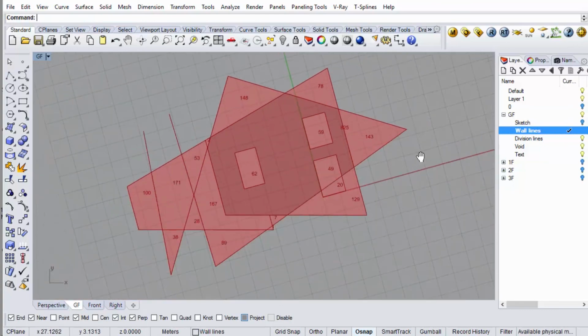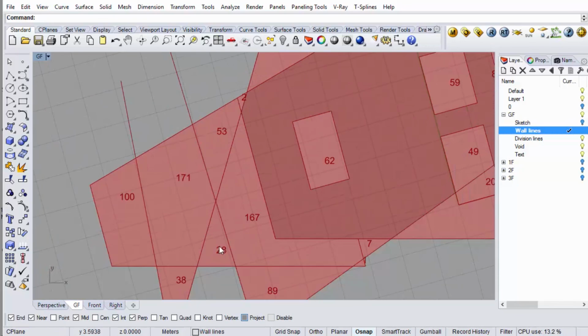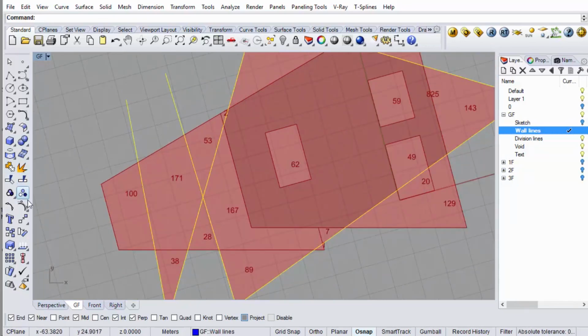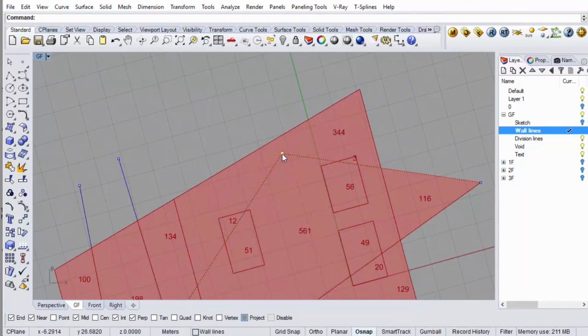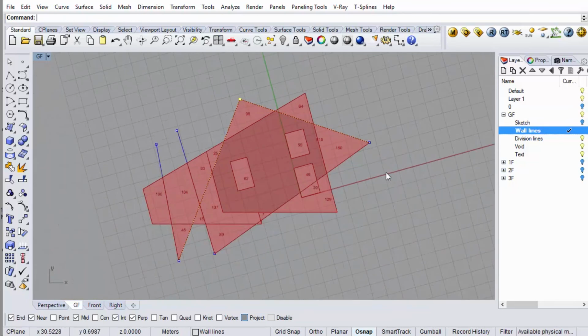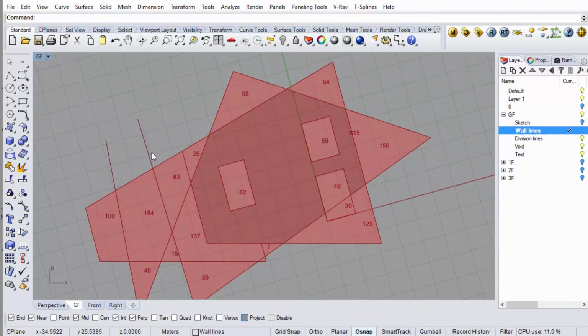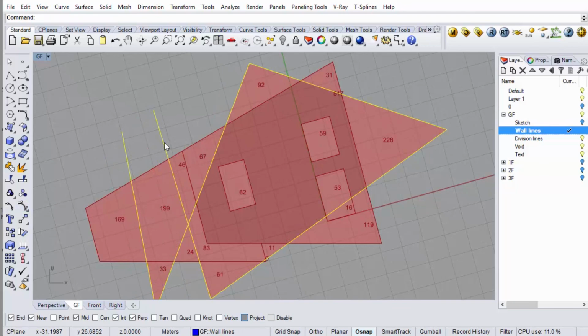See, all of these have their own areas and all of them are being calculated in real time. So you can move any point, doesn't matter the geometry. And you can get quite Libeskind here if you want. And everything is getting updated in real time, so you have a real sense of what type of spaces you're creating. And this is a real lifesaver in, say, maybe a competition where every bathroom is specified to an exact area, and this is perfect.